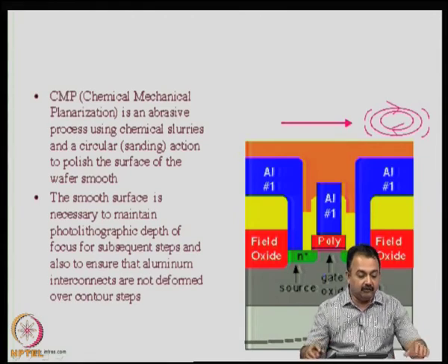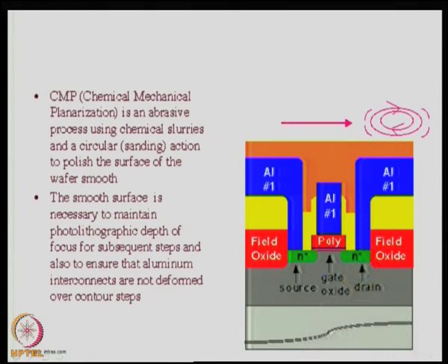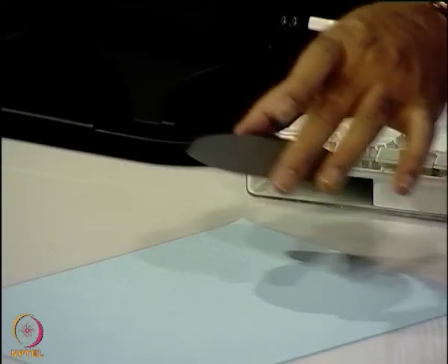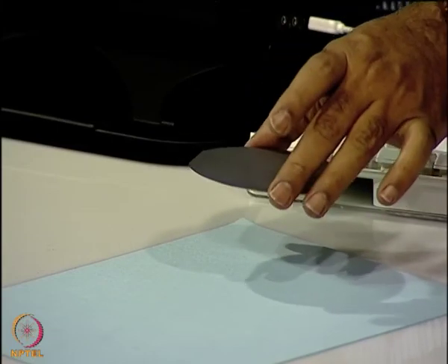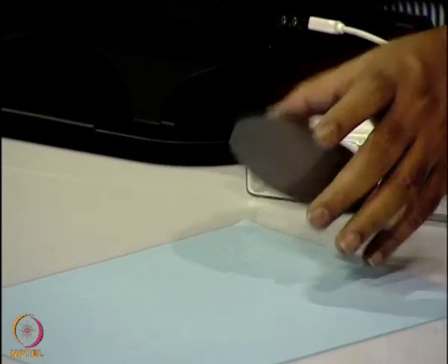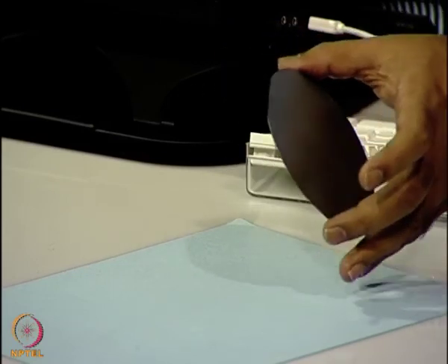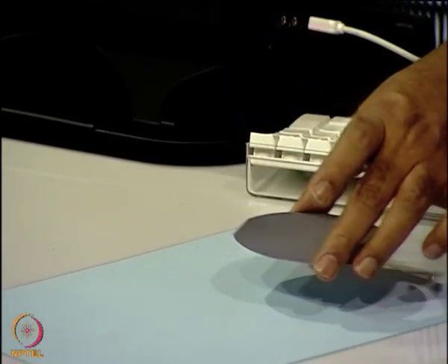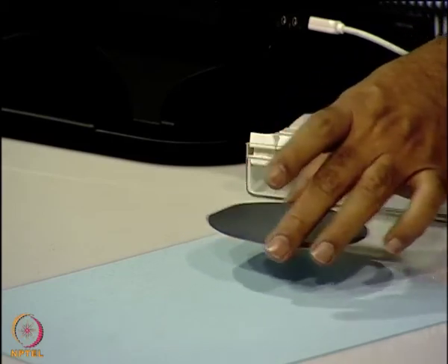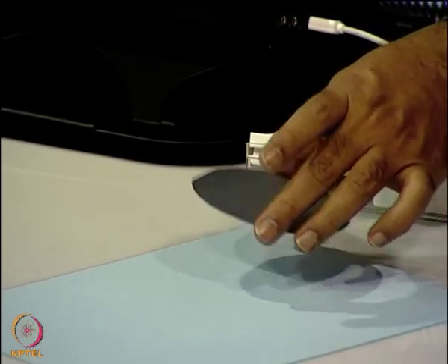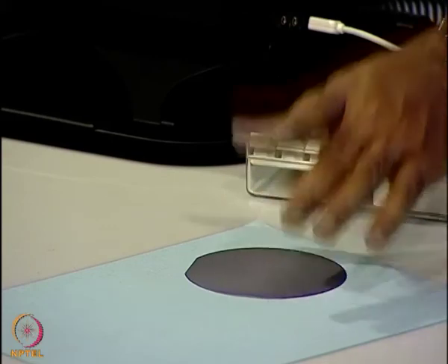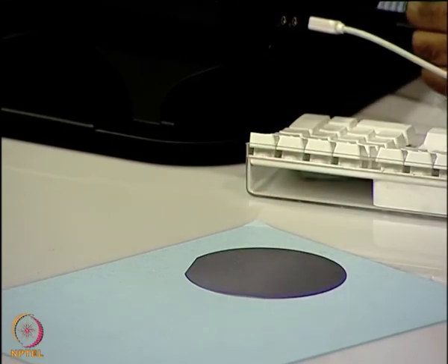That means, you take the wafer and it will be ground on an equipment, until you remove the excess copper from the surface. So, if this is the grinder surface, there will be a wet slurry coming and falling on this material. There will be an abrasive material that is used, and the silicon wafer is polished continuously, inspected, and you have to see whether we have reached the designated thickness.